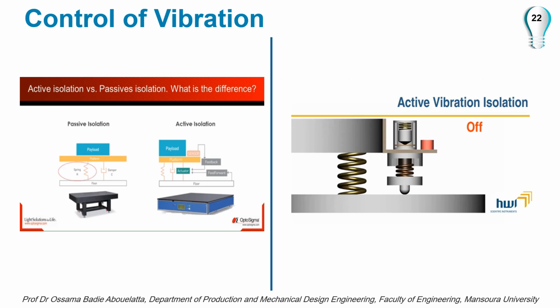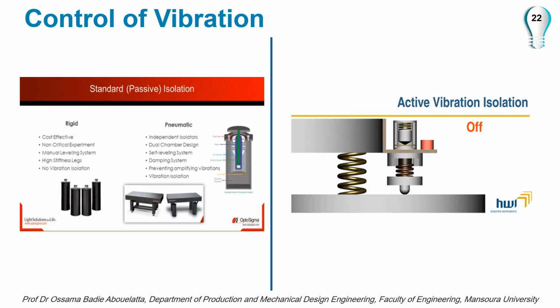The spring, the isolator, reduces the magnitude of floor vibrations reaching the isolated payload, whilst the damper dissipates the vibrations amplified inside the isolation system. Passive vibration isolation systems are rather affordable and powerful at dampening high-frequency vibrations, however they won't be suitable for applications in which low-frequency vibrations are a concern. Passive vibration isolation systems have an extended settling time and are sometimes hard to control.